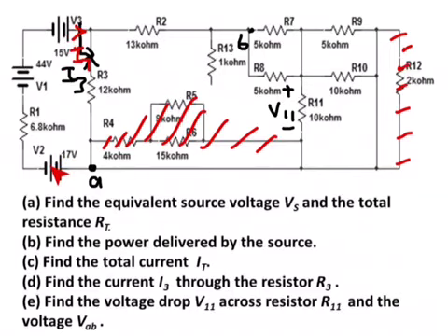And this voltage is trying to push current in the clockwise direction. All these changes, you can make them immediately. Replace these three sources by one source. Replace these two resistances by one resistance of 2.5K. Replace these three resistances by one resistance of 2.5K. Eliminate this branch, eliminate this resistance, and redraw the circuit, and the circuit will look way simpler.